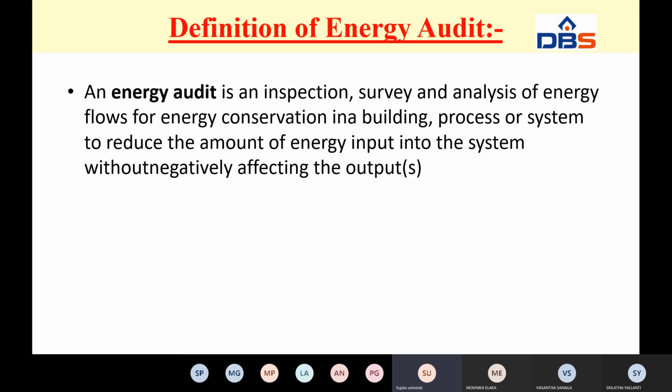During an audit, an expert examines the building for energy leakages, such as air leaks, as well as ways to maximize energy usage, such as more efficient lighting and heating and cooling systems, and how much energy they consume. Like that they audit in the different sectors.